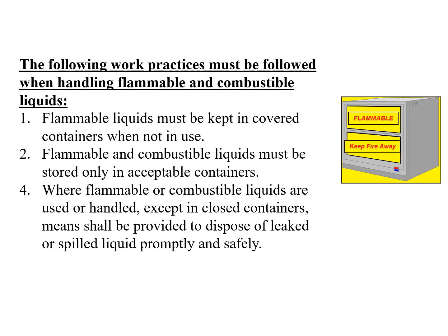The following work practices must be followed when handling flammable or combustible liquids. Flammable liquids must be kept in covered containers when not in use. This is very important, always cover them, because the vapors can float into the air. These liquids must be stored in acceptable containers. As I mentioned in the last slide, these are special containers, not a normal water bottle or empty soda bottles. They are not to be used.